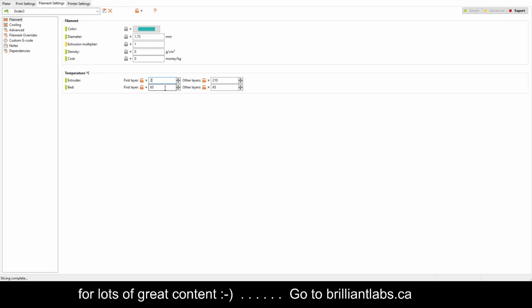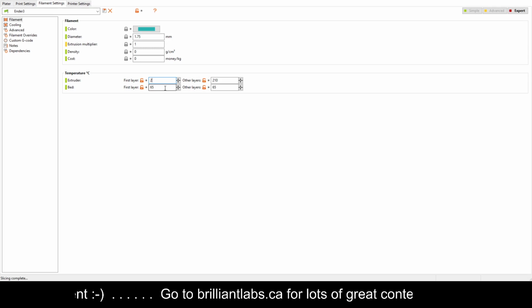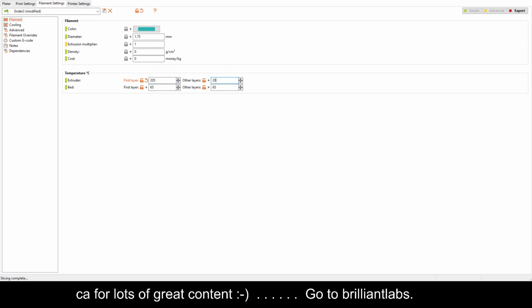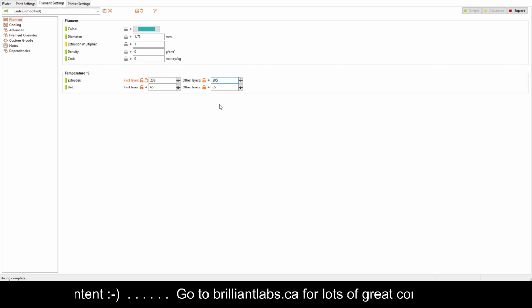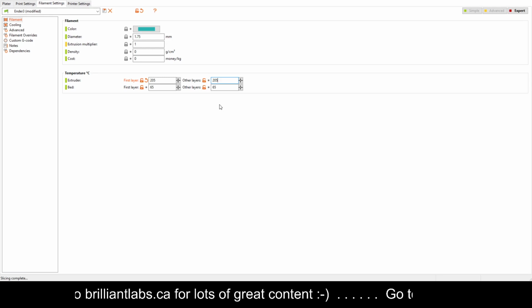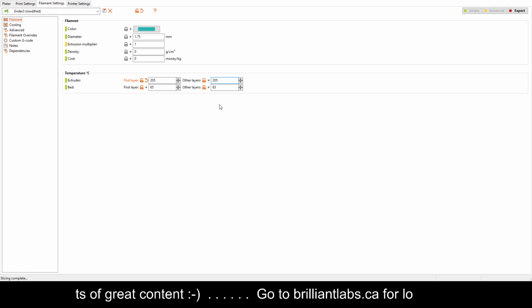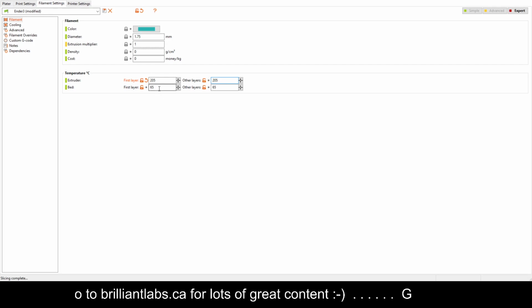If you don't know what it is, if it's PLA but you're really not sure how good it is or what temperature it should be done at, 205 or 210 is probably a good number to start at. And you can experiment from there. The print filament that I currently have in my printer seems to print better lower. Some of the stuff we have at our office seems to want to print higher. We print some things at 220, and yet it seems like it's standard PLA.